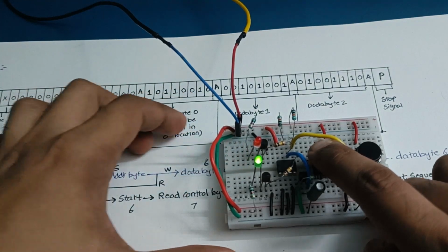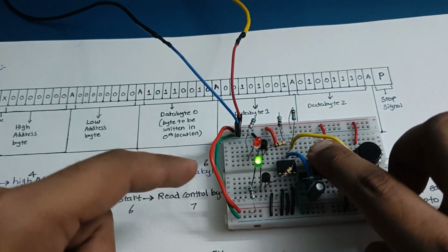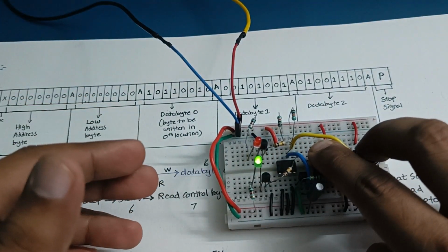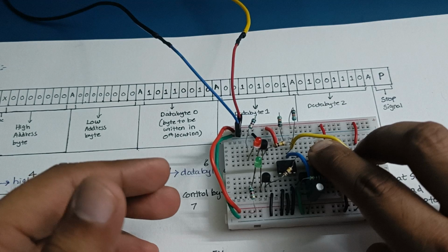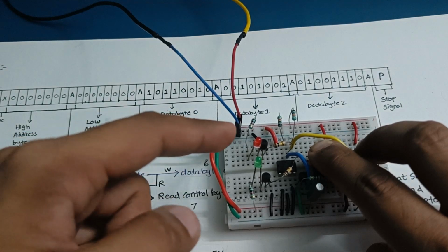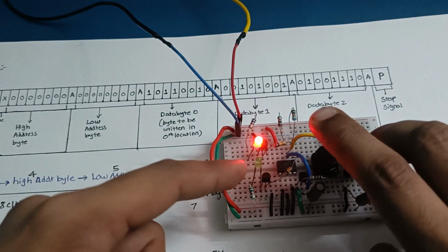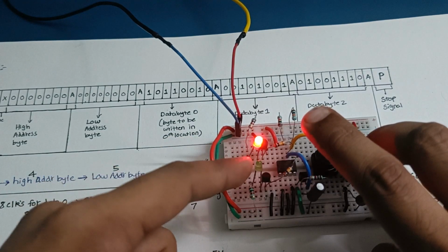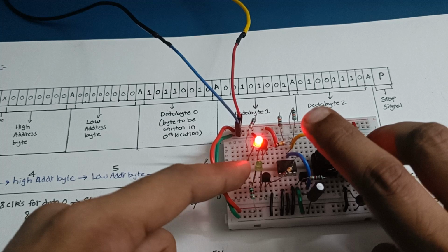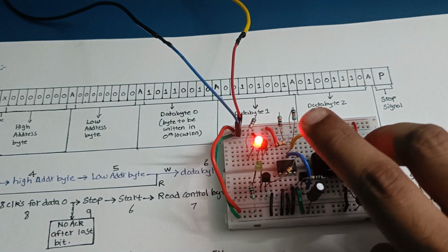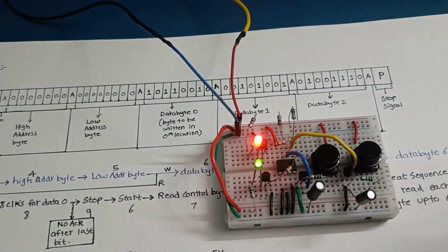And now see how to generate the stop signal. To generate a stop signal, first you have to shift in a 0. So you have to pull down the data line and release the clock, which will give a rising edge and store a 0. Then, when the clock line is high, you have to give a low to high pulse on the data line. So right now the data line is low. I will release the data line and this will stop.